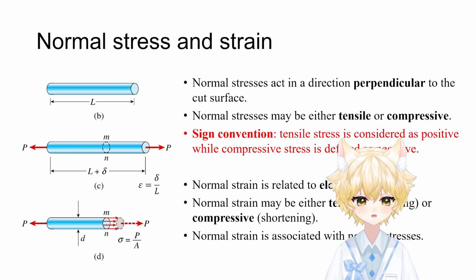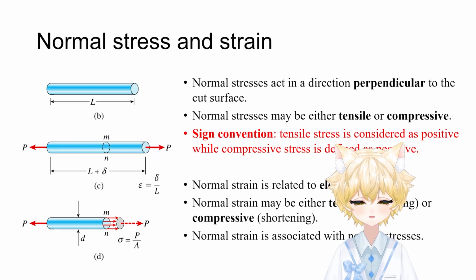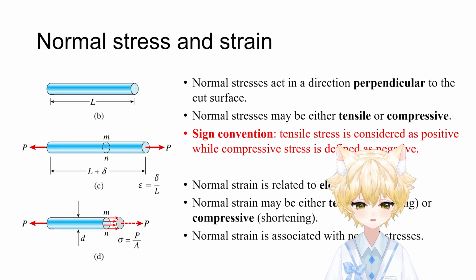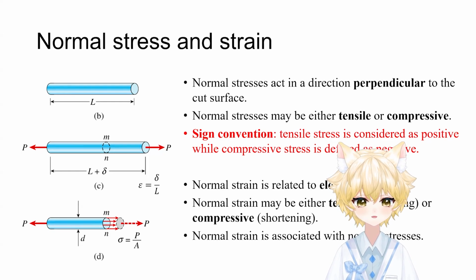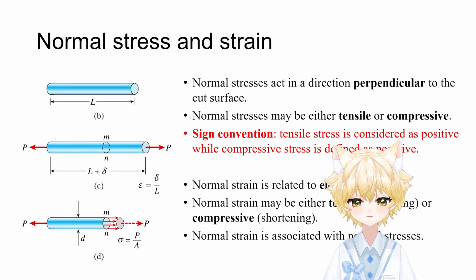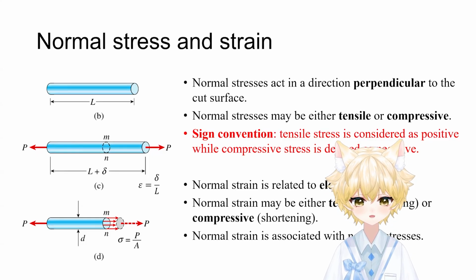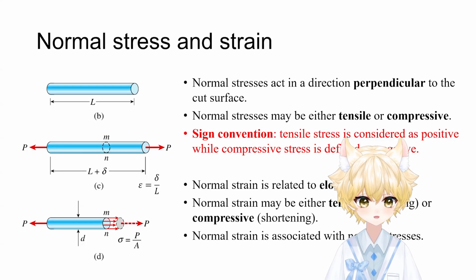Normal stress is just our way of averaging that internal resistance perpendicular over a specific area. Normal strain is just a way to quantify that physical elongation, right? We use stress and strain to eliminate the size effect, and let's focus more on the material itself, right? That's the reason we don't use force or displacement.